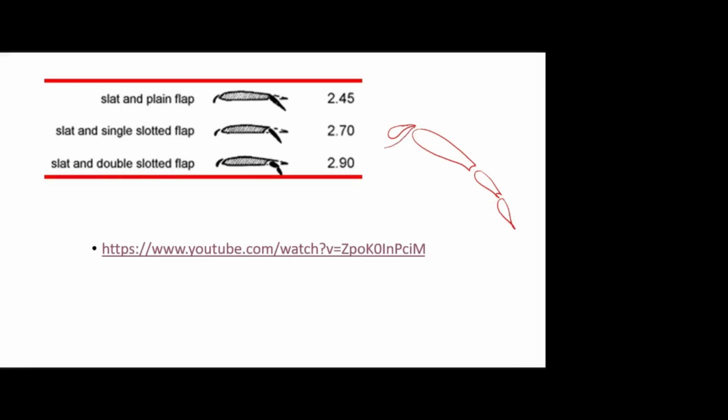So here there is a flow through this. This gap is called the slot. Okay, this gap is the slot, and this is the slat. Leading is slat, the gap is slot, and this is the flap. And again, this is also a slot. So if you use a slotted flap and leading edge slat, there will be a high energy flow in this gap also. That maintains some attached flow on the airfoil and flap, so that we can reduce the drag and we can get more CL. That's the idea of the slot introduced in the flap and slat.